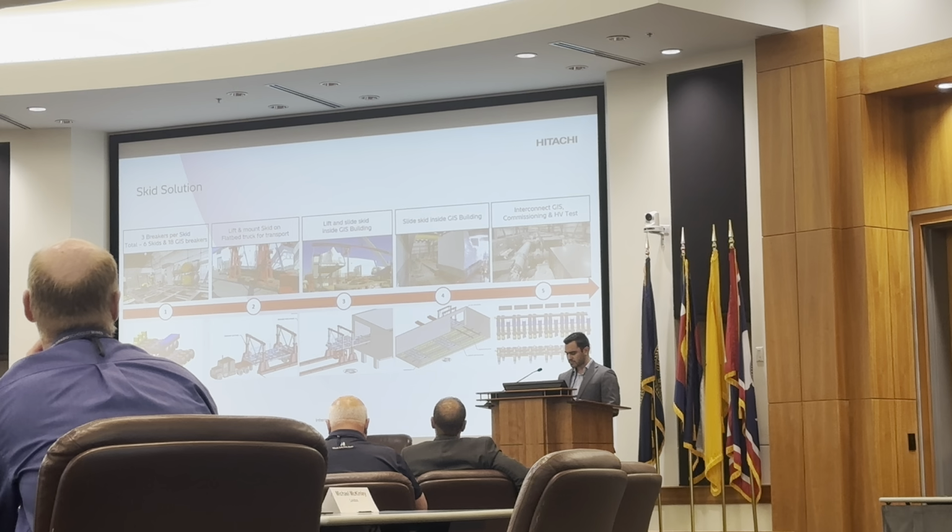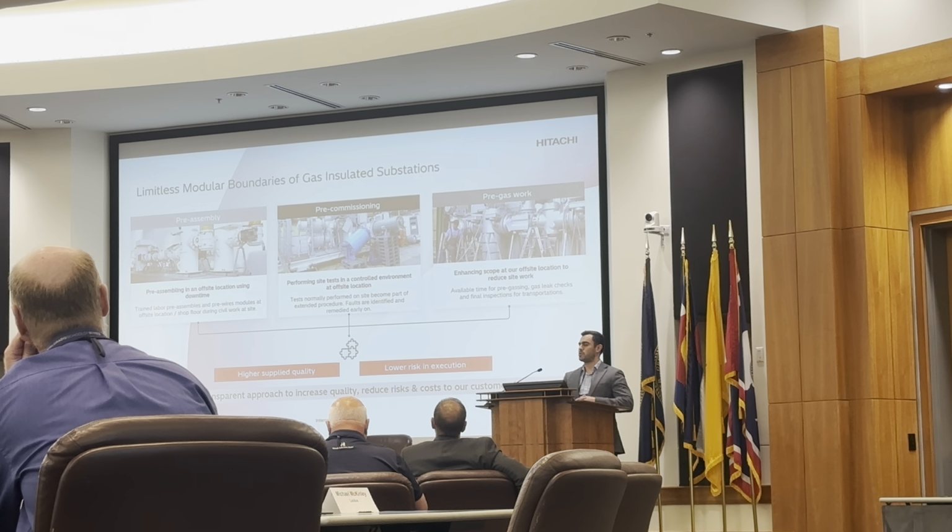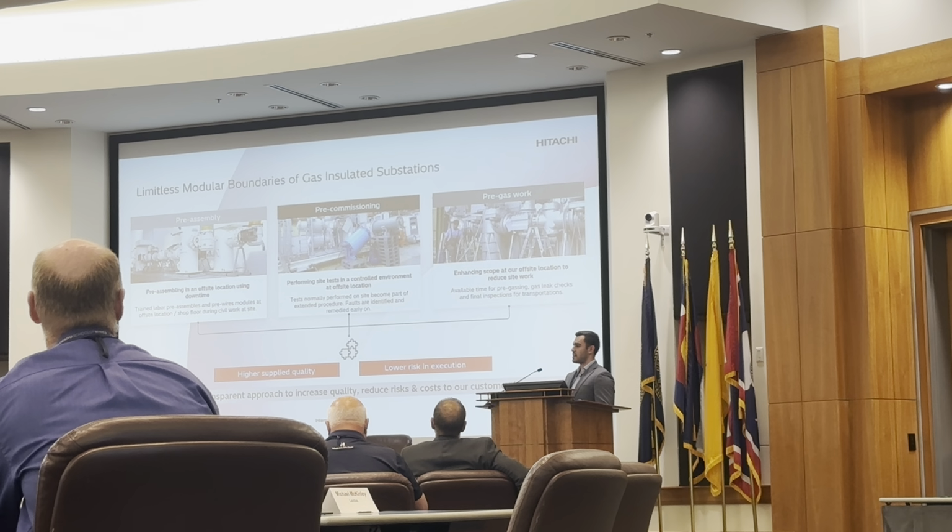Pre-assembly, pre-commissioning, pre-gas work. Everything is done beforehand, so anything that has to happen on site has already happened at the warehouse. This presents lower risk in execution, and if there were to be any errors during the commissioning side, or a missing piece or anything that happens during the commissioning or installation phase, that is the best time for it to happen, because this can easily be mitigated. Okay, and it's not going to delay the energization dates.